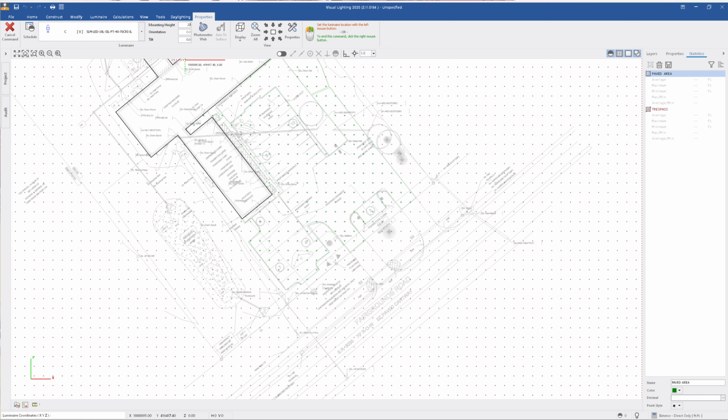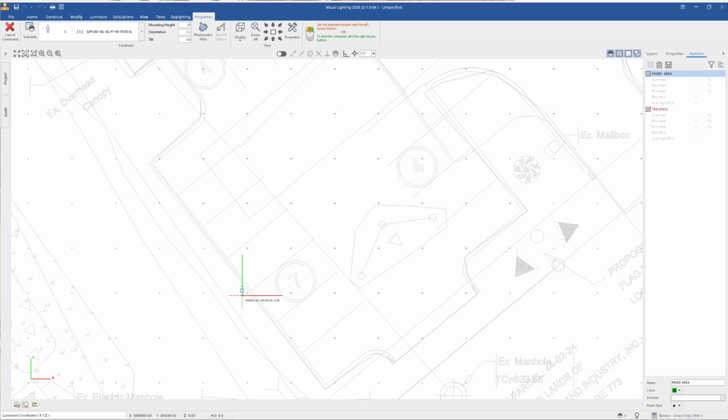Okay, so now I have a type 4 forward throw light fixture at a 20-foot height, and I'm going to put it right on line with a stripe on a parking lot. That way, less chance of a car hitting it and bending the pole. And typically, we like to have the poles about 3 feet off the face of the curb. So I'm going to put it just like that. So I angled it, rotated it, accepted it. It's ready to go to the next one if I want. I'm going to exit out of there.